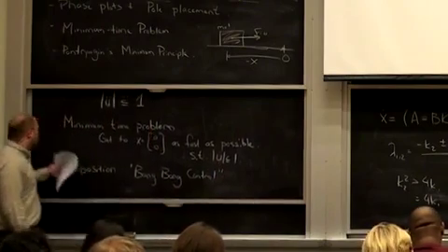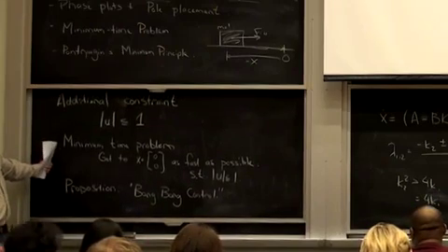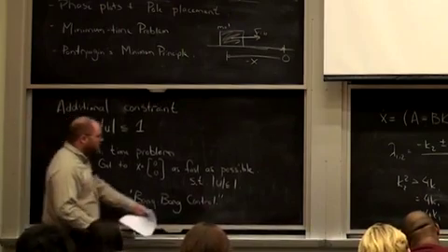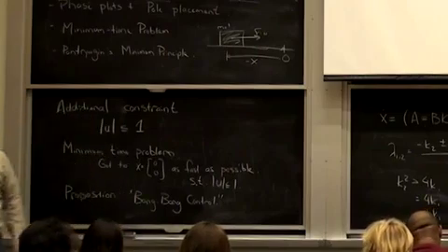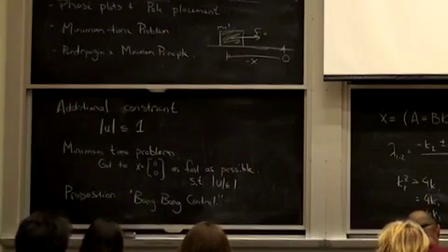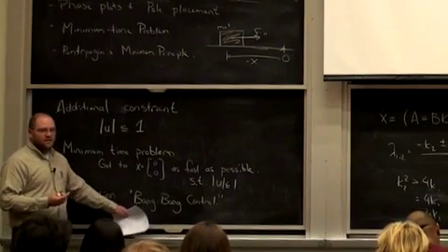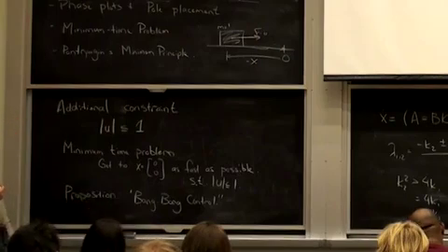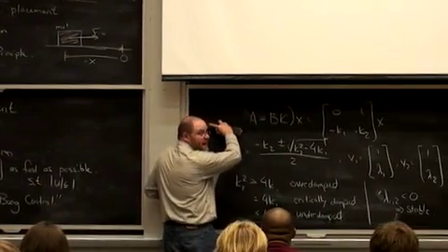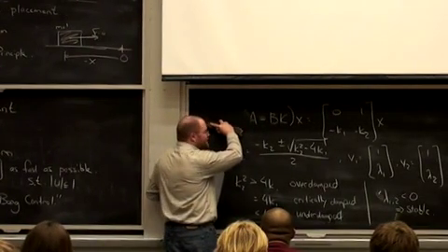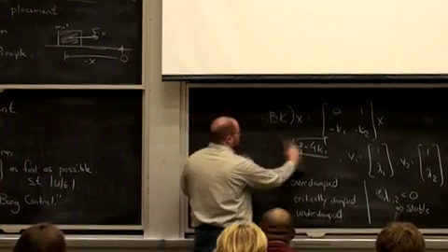Okay, bang-bang control. You might hear people casually say bang-bang control is optimal, and that is very common if you have hard limits on your actuators. It's very common that the best thing to do is to be at those limits all the time. If that's the way you've defined the problem, bang-bang control solutions are pretty ubiquitous. They don't always work that well on real robots because actuators don't like to produce zero, infinite force, or max force and then negative max force within a single time step.